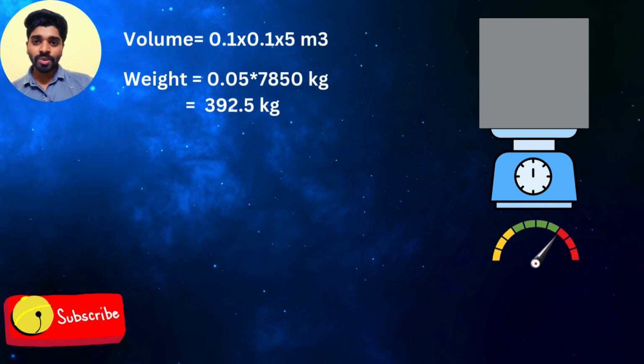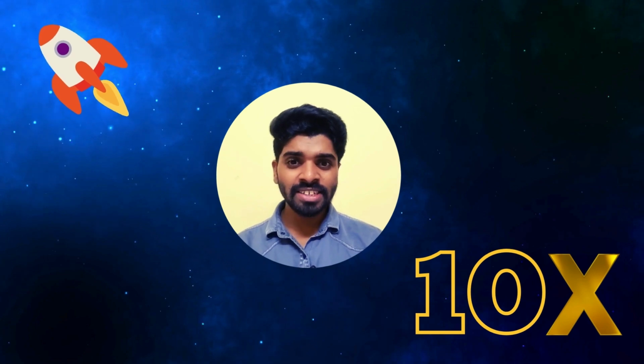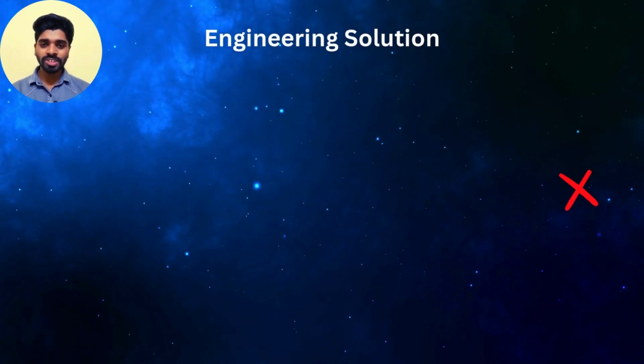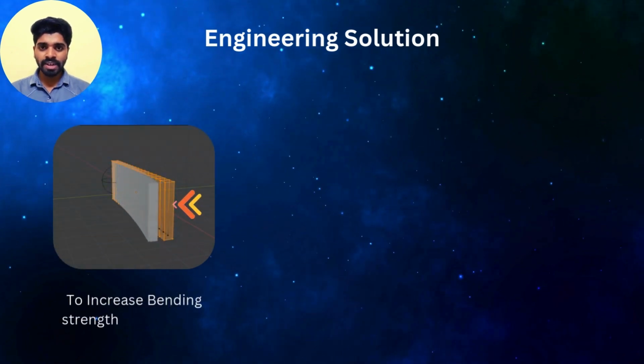Now if we make this steel plate a square section, means its depth and thickness are equal to 100 mm and its length is 5 meter, then its total weight will be around 392.5 kg and its total cost will be around 19,625 rupees. So you can see that just to increase its bending strength in the minor axis, we have to pay around 10 times. Is it worth it as an engineer? Since we are engineers, not labor, we always have an alternate solution for that. We just have to increase its bending in the minor axis and prevent its buckling.